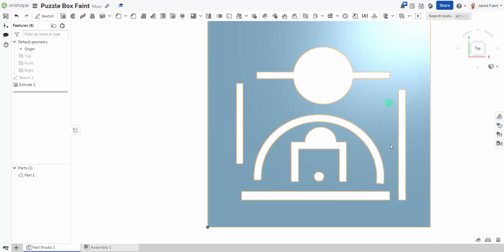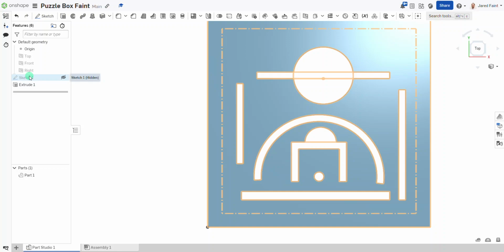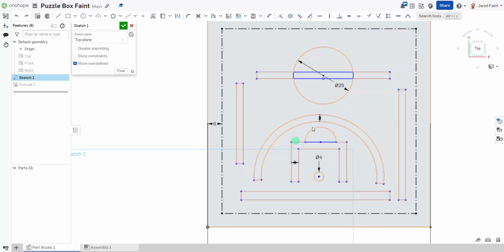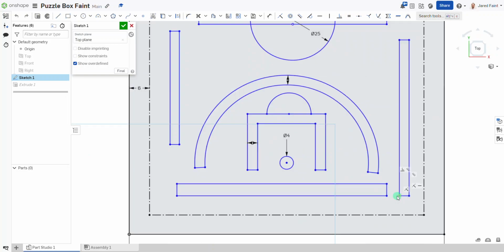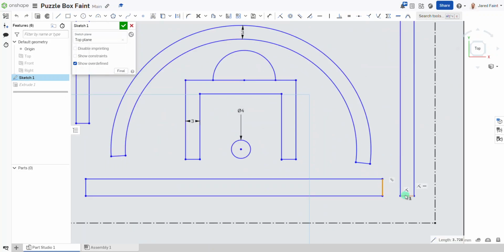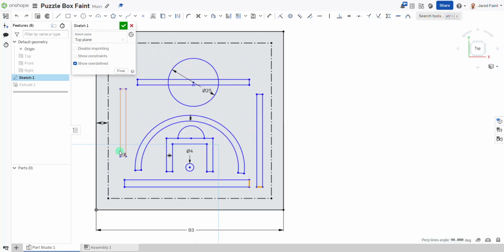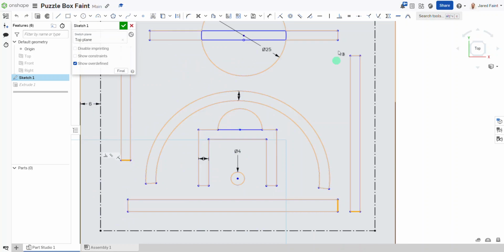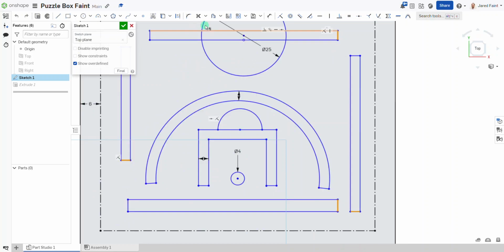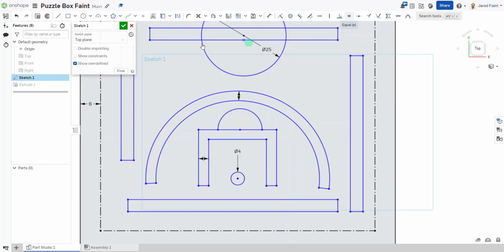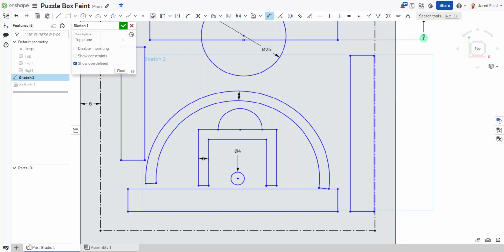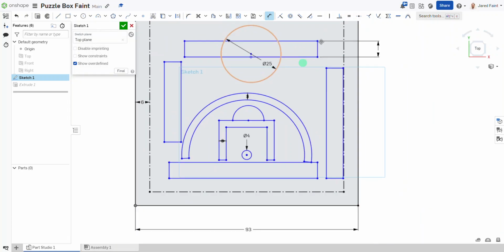Now, there's a few things that I can do to make this a little bit neater and tidy this up. We notice that all of these lines around the side, I can select the end parts there, so 1, 3, and 4, with the offset there. I'm going to make these all equal. Then if I do one dimension, just on that one, I'm going to make them 7 mils, and that's going to be quite fat, but that means they're going to be able to fall through if I want them to.